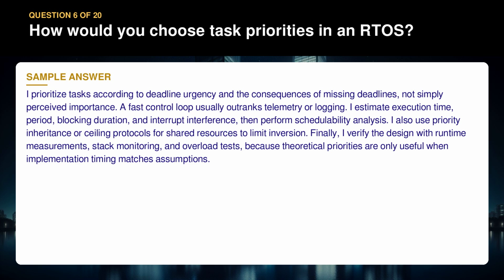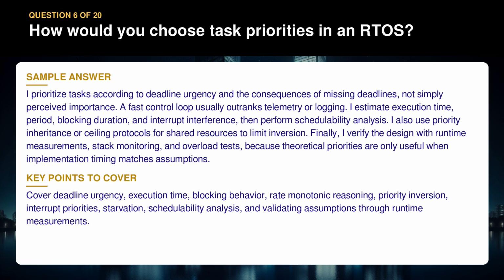Finally, I verify the design with runtime measurements, stack monitoring, and overload tests, because theoretical priorities are only useful when implementation timing matches assumptions. Cover deadline urgency, execution time, blocking behavior, rate monotonic reasoning, priority inversion, interrupt priorities, starvation, schedulability analysis, and validating assumptions through runtime measurements.